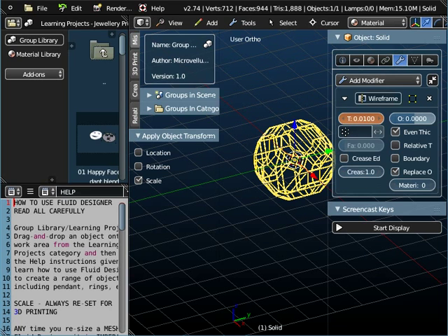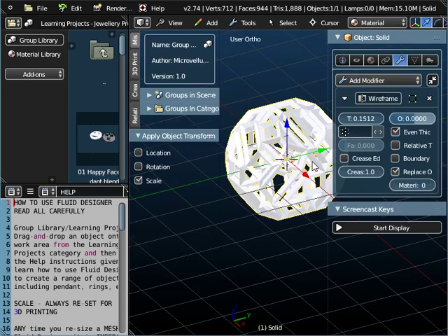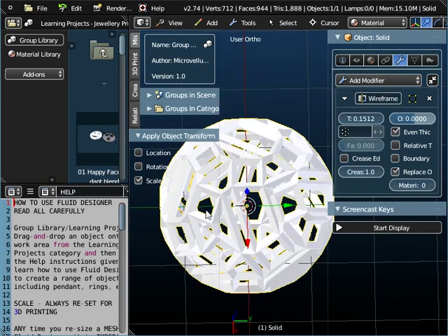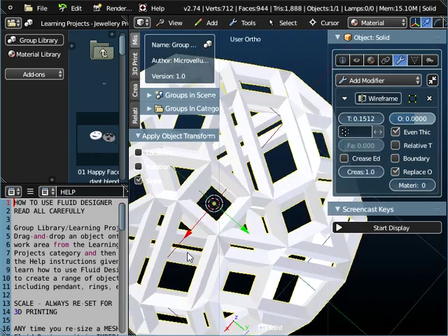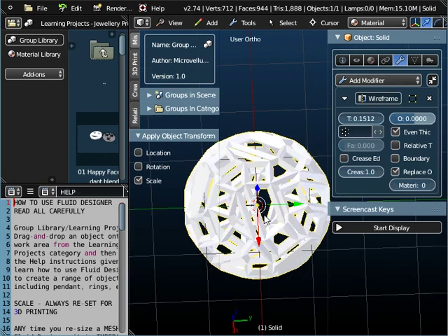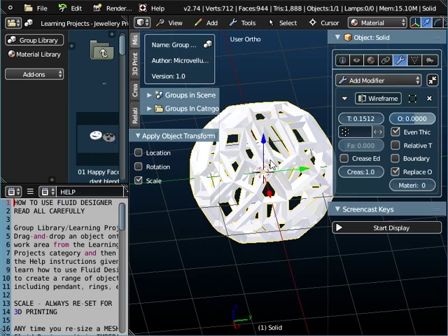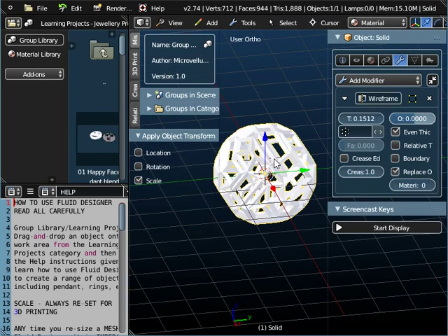You can see. Now clearly these are going to have to be thick enough to print. So some of these objects, you're not actually going to be able to print them. You do need a thickness of about 0.6 or 0.8 millimeters. Depends on what you're printing, what material you want to print in. So you can't just print absolutely anything. You do need to size these up to a certain value. So some of these shapes, you just can't print.